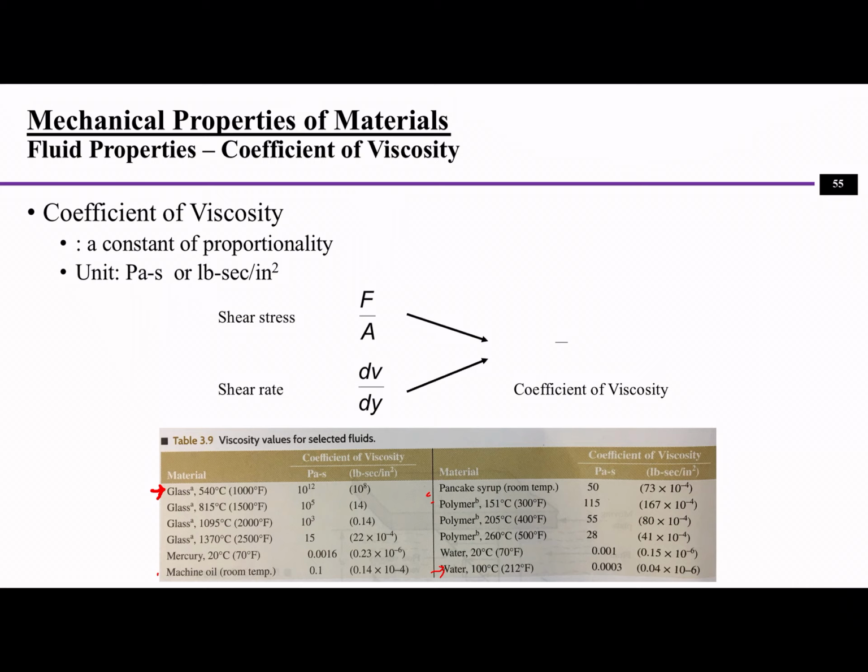An important application for viscosity is actually in the pipeline, when you are transporting oil. A lot of times crude oil is transported by pipelines, and you need to constantly measure the viscosity of the oil to make sure you have good quality, not much contamination, and to detect if there's a leak or other changes in the environment or temperature.